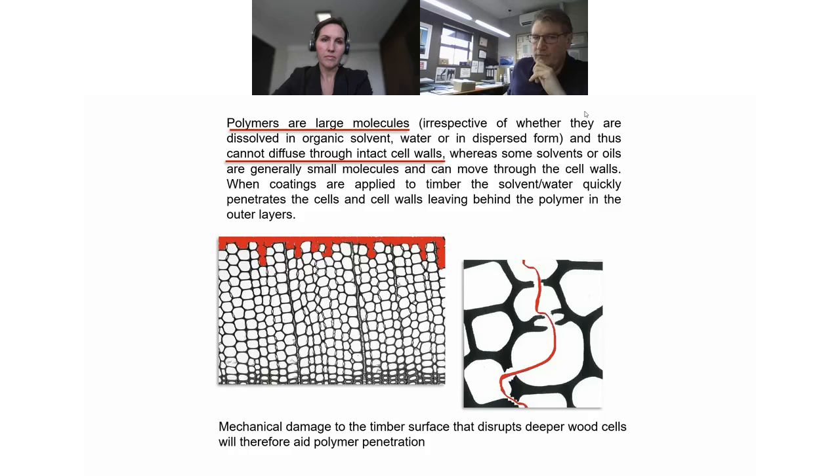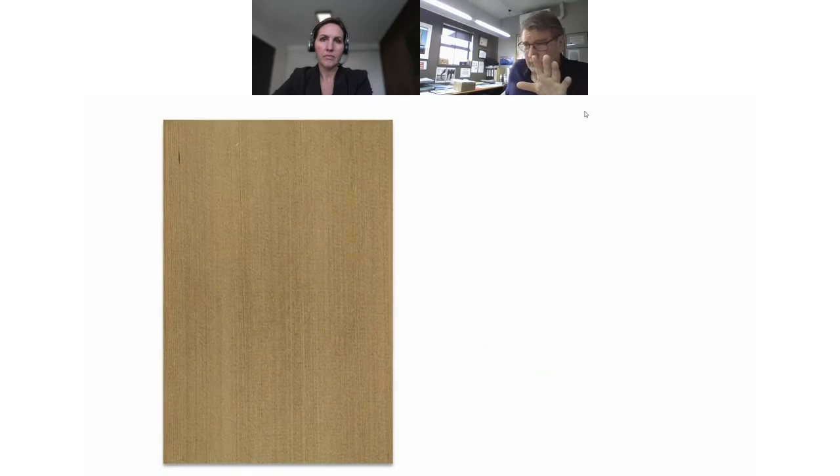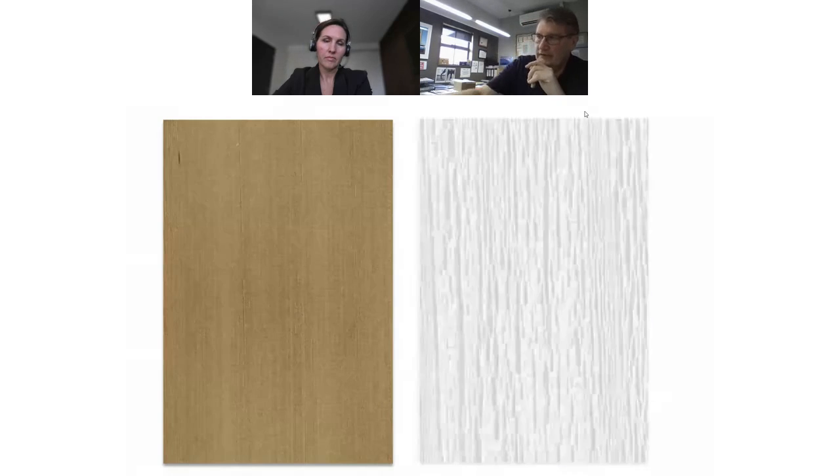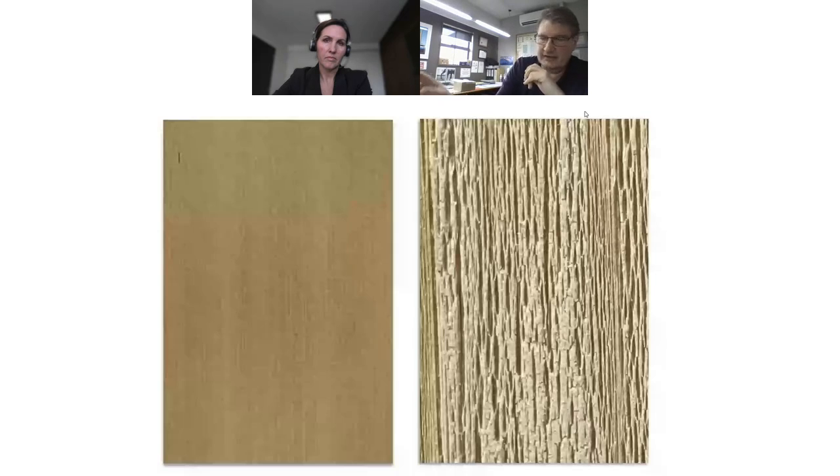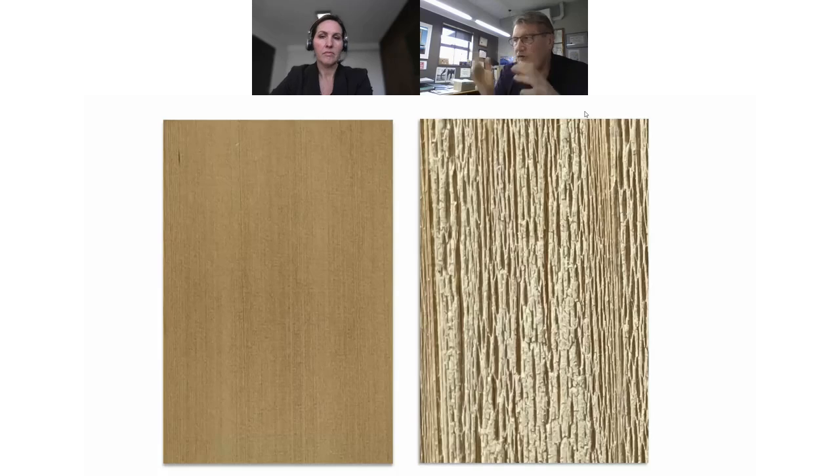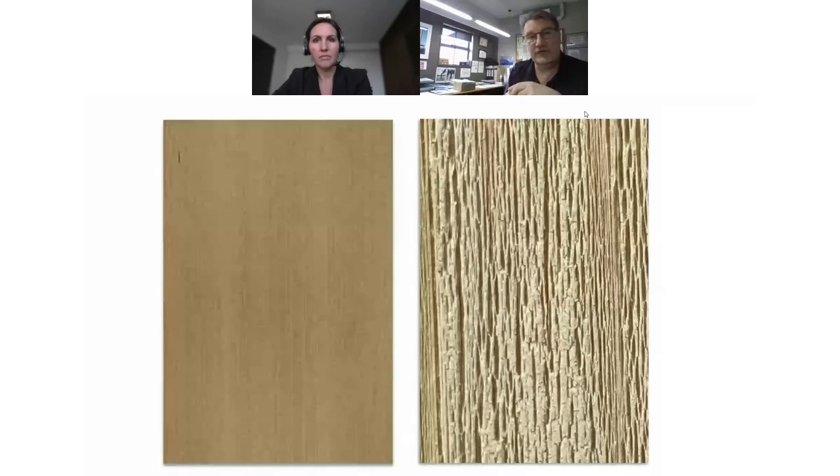And here's an example, and I'm just showing you this because it helps show the cell structure of timber. There's a brand new piece of timber. This is cedar for this example. And then this is a close-up picture of after 6-9 months outside. And you can see the longitudinal cells. Some of them are broken open, some of them are gummed up. It's just a really good picture, which I use for my students to show them the elongation of the wood cells. But that's also what weathering does to timber, which we'll spend a bit more time on.